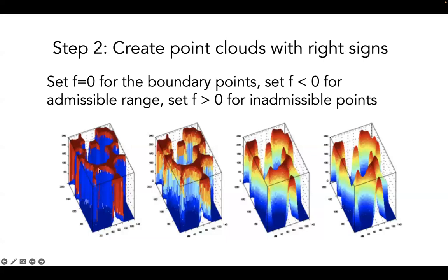This is a geometry just for cartoon purposes. If I have a binary function that indicates what is inside and outside, I just need to solve a level set function to enforce the norm of the gradient of f equal to 1, and I will get these functions. Then I would use the point cloud of these level set functions to learn the yield surface at different points.